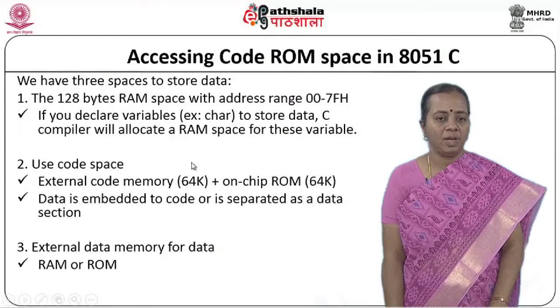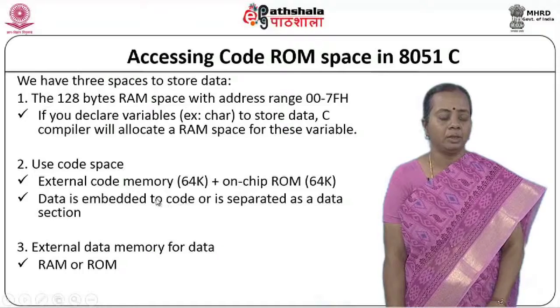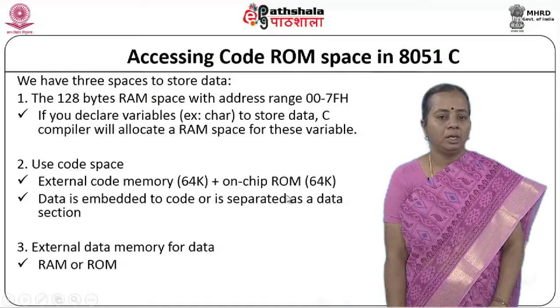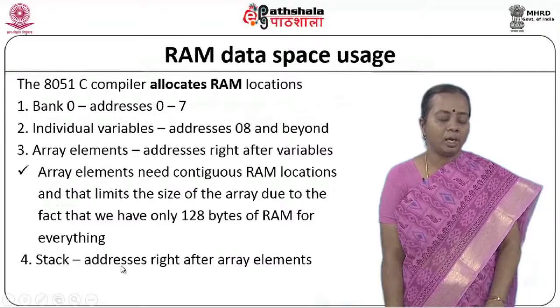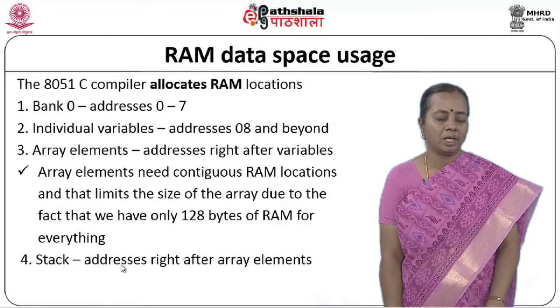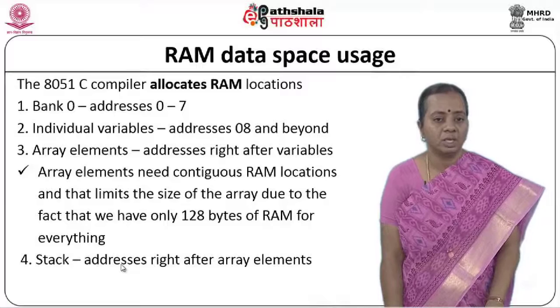Because the system has the code space, we can either use the code space on chip ROM, or I can use external memory. So, I can make use of external code memory, or on chip ROM also, or we can use external either RAM or ROM for accessing or writing data over there. This also can be controlled by us by writing it in the code declaration itself. If I change the declaration, then I can choose whether I write inside or outside, with the code memory or with the data memory. So, all those things can be controlled by the syntax we use in the declarations.